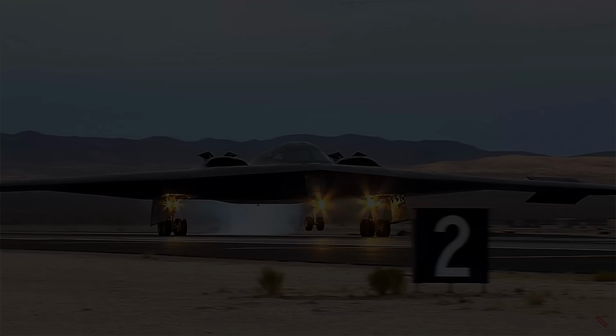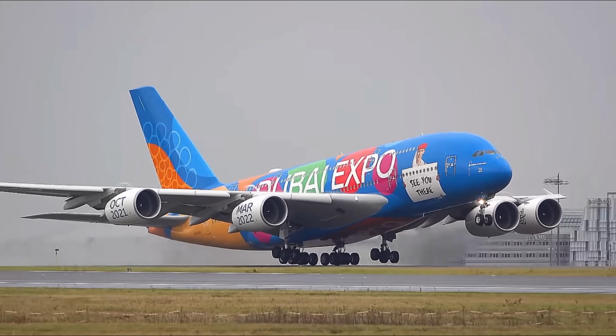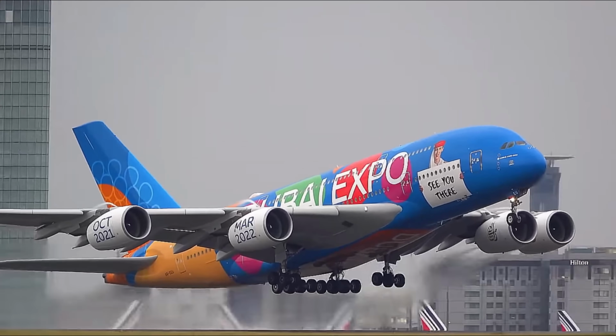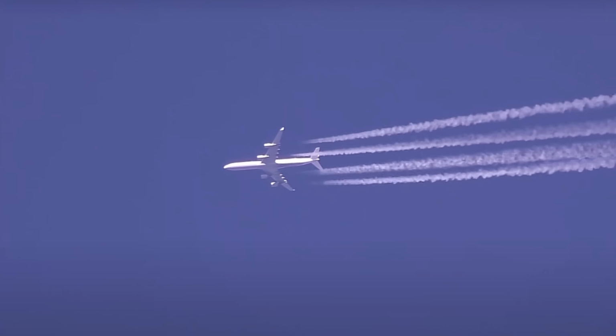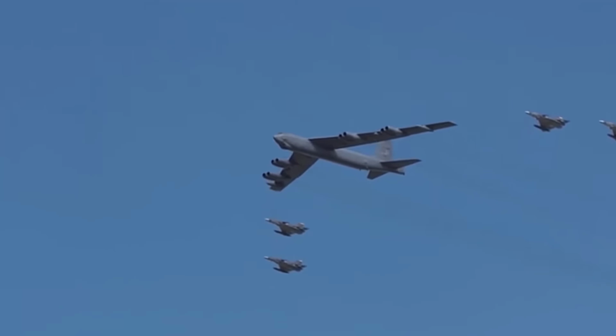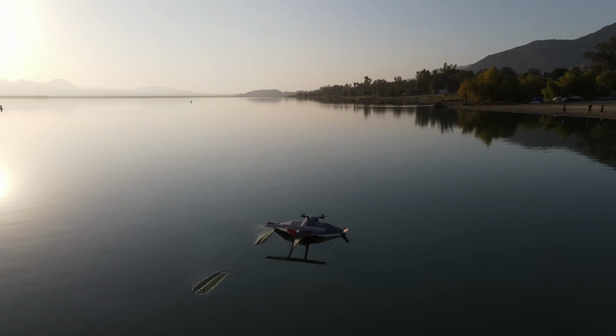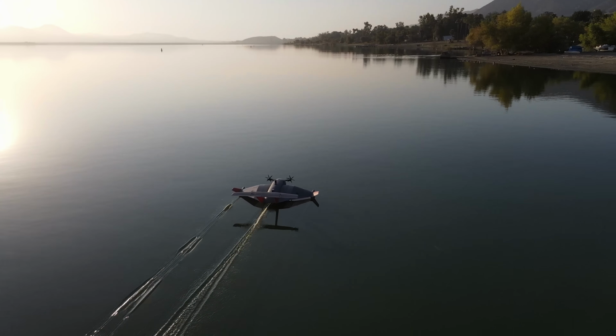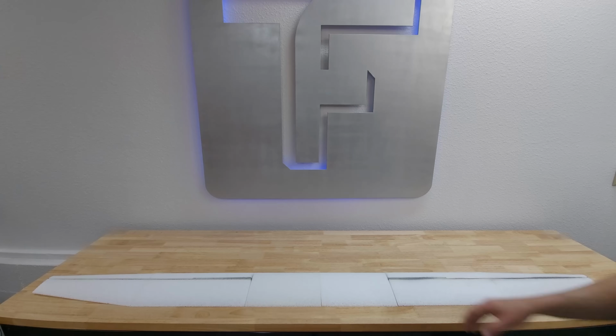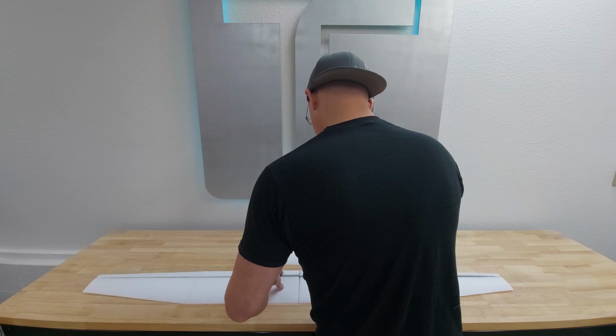Mind blown. Why? Because most aircraft have wing size set by takeoff and landing requirements, not by cruise, where the aircraft spends the majority of its time. Almost all aircraft wings are larger than they would need to be for their most efficient cruising speed. If I can now create a smaller wing and still land at the desired speed, my cruise drag goes down. The wing could potentially be 25% smaller than normal.